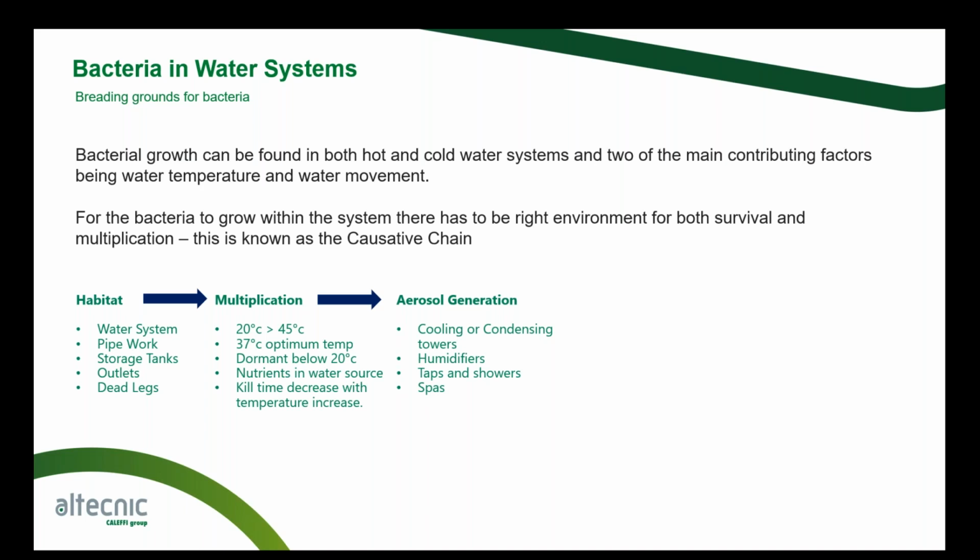Now, these create their own issues. If you are not chemically treating the water, your spa is sitting quite nicely at a temperature of 37, 38, 39 degrees. If you've not got any kind of bacterial treatment within there, you are giving out perfect breeding ground, shall we say, for bacteria, along with the aerosol generation. You get the steam, you get the very small micro bubbles that come off there. That then starts to become aerosol generation.